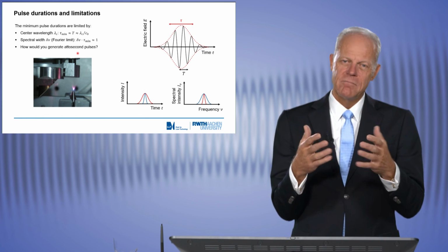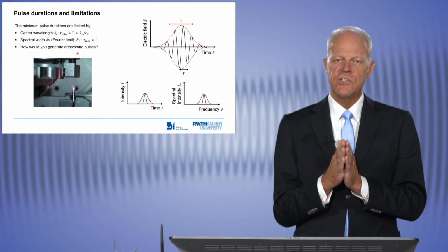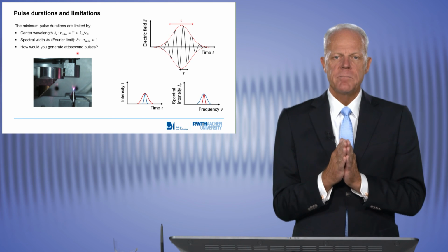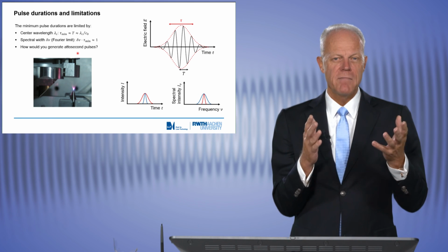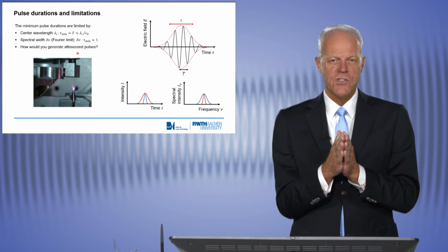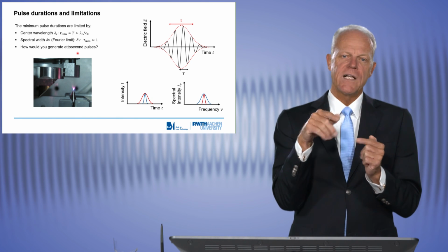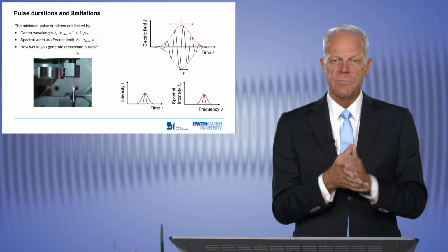In reality, picoseconds, sub-picoseconds are sufficient for most materials processing applications, because we have an optical penetration depth, which is in metals about 20, 50 nanometers, so it doesn't make sense to use pulses which result in shorter thermal penetration depths compared to the optical penetration depths.